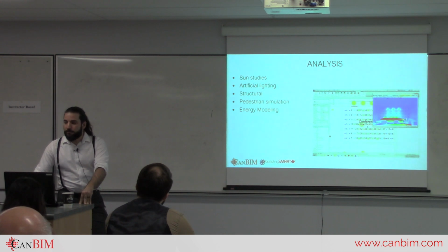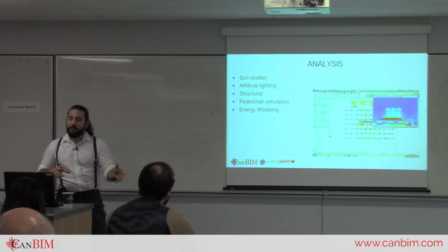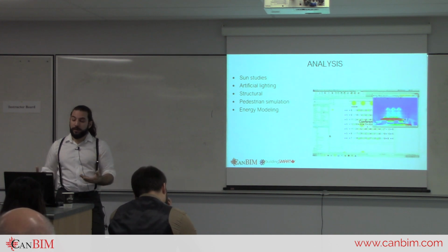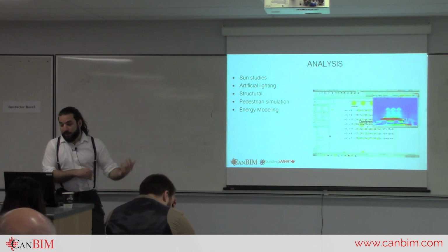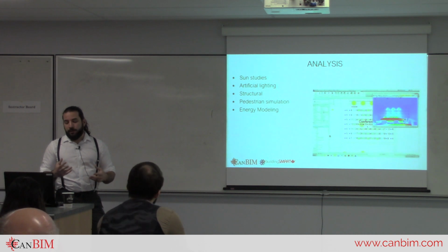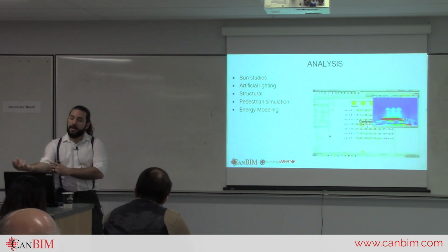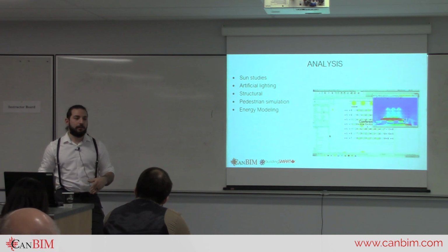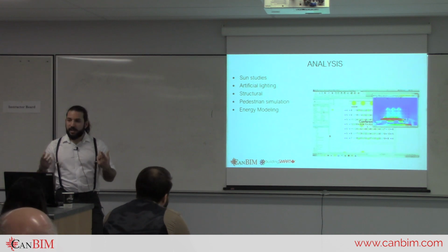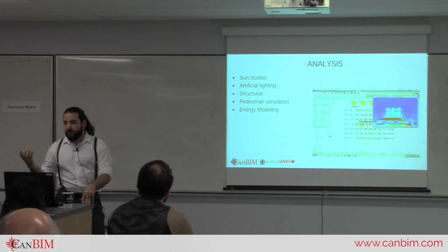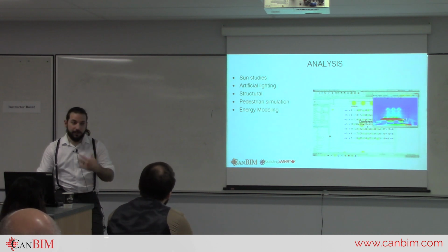It means like bringing them back to other software, or you don't get to produce a drawing set from them, but you are still modeling an intelligent building, basically. You're just entering all this data about the loads that are going to be on your columns, beams, and you're defining items, and you're defining their sections. So it is actually definitely BIM software, at least in my mind.